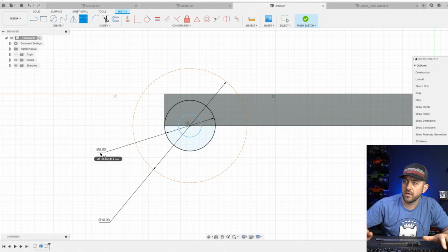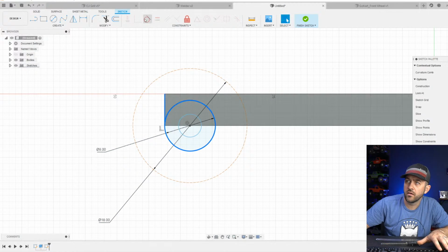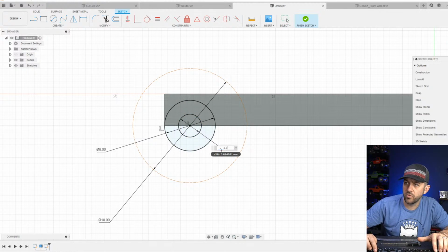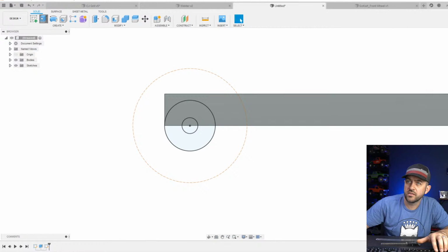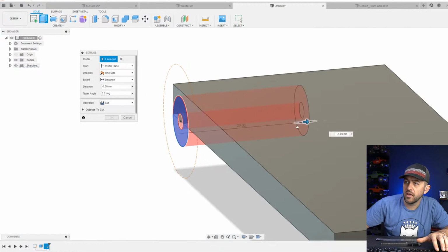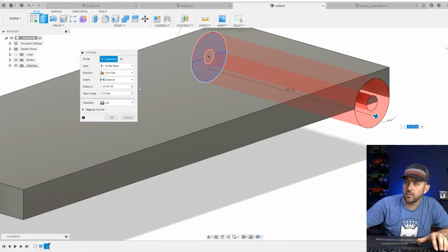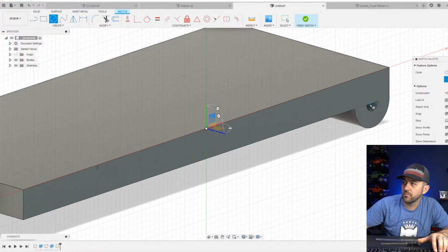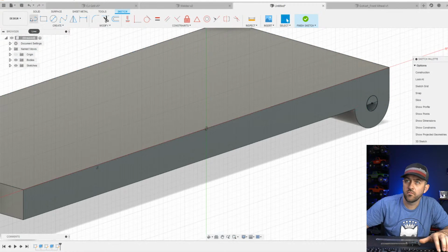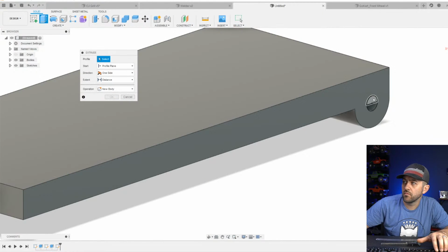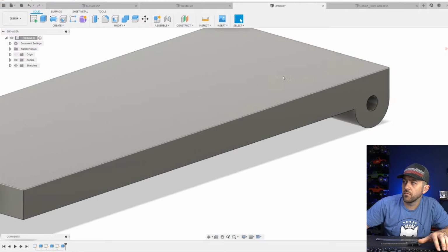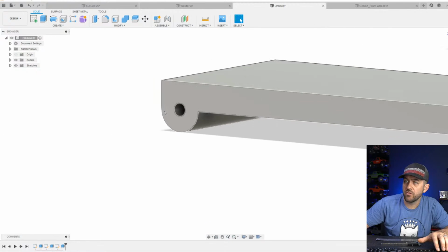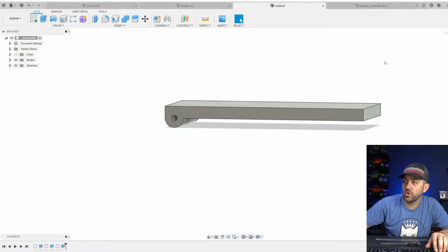Let's go, yeah, 8 millimeters seems good there. Inside, we'll go 2.5. This is just going to be where we end up with a 35 join. I know it didn't create the axle hole properly, but that'll give us a way to mount our wheels, our rear wheel at least.